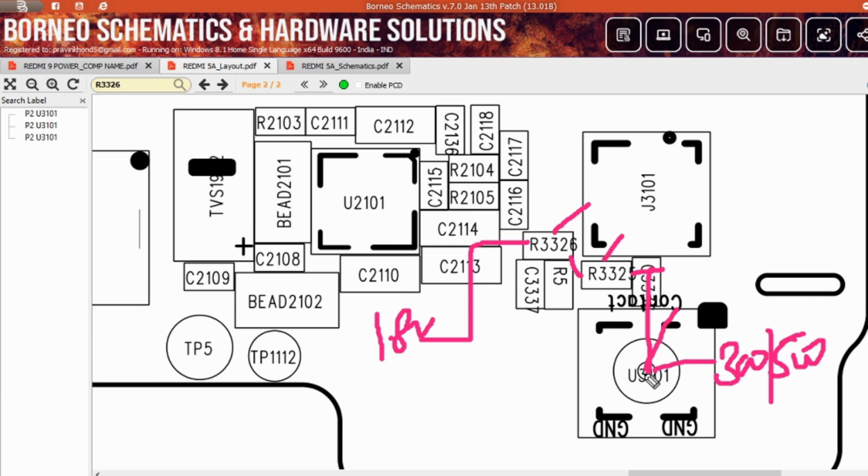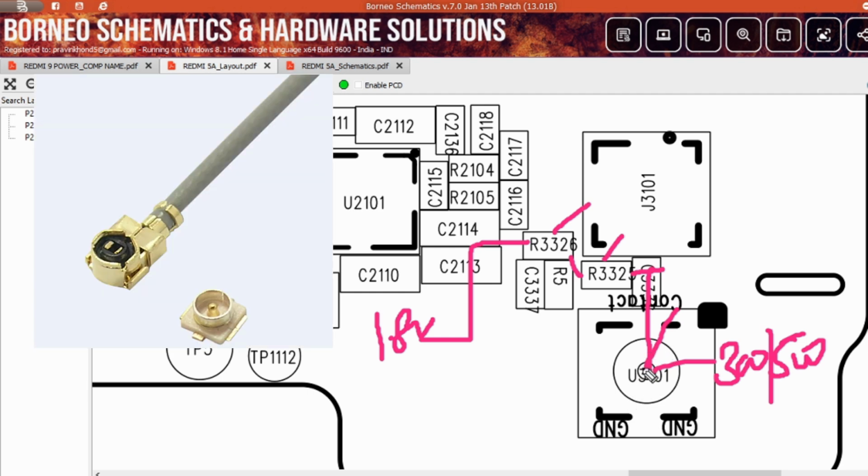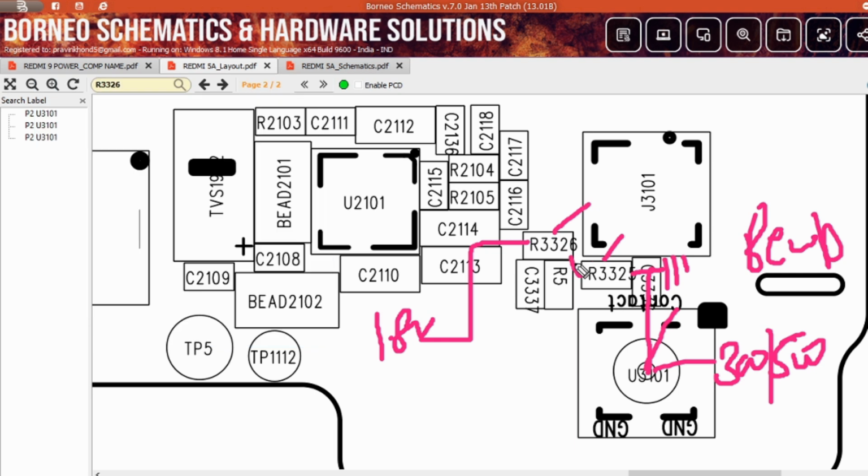After you connect the RF cable, this point is connected with the ground. If you remove the RF cable on the main motherboard, this point shows 300 to 500 diode value. If you connect the RF cable here, this will show you a beep or 00. Clear? Now R2 is connected with the ground after connecting the antenna cable, right? After that one line emerges in between, according to the divider circuit formula. In this line you will get 0.2 volt. This line goes to the CPU.